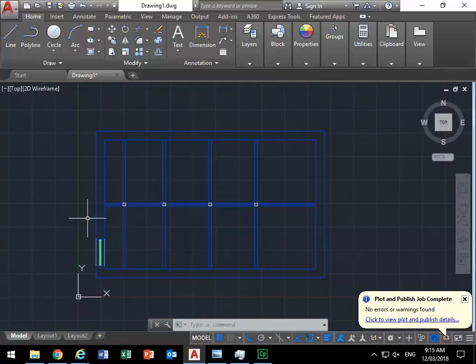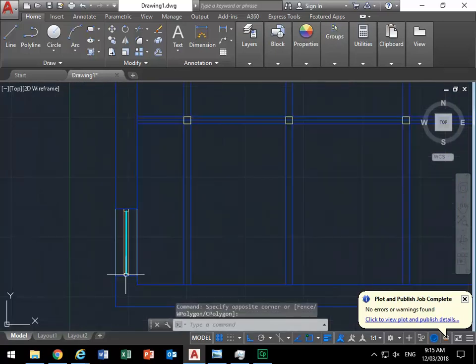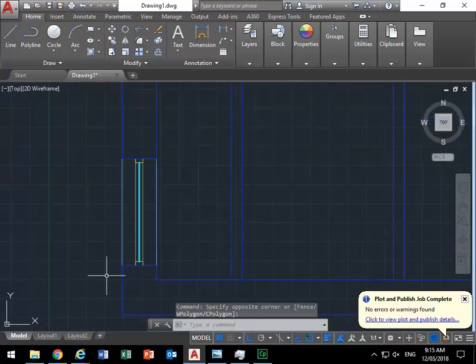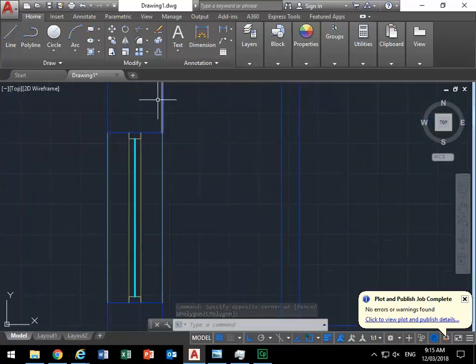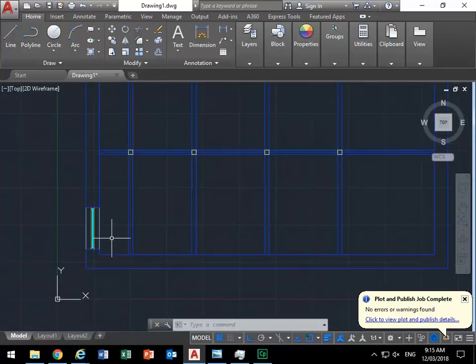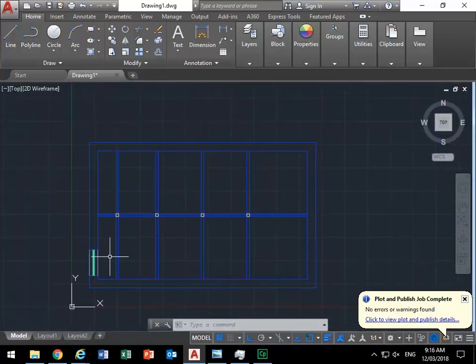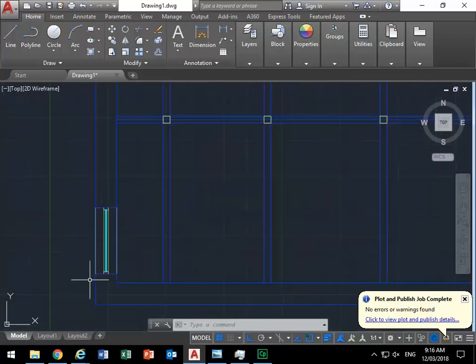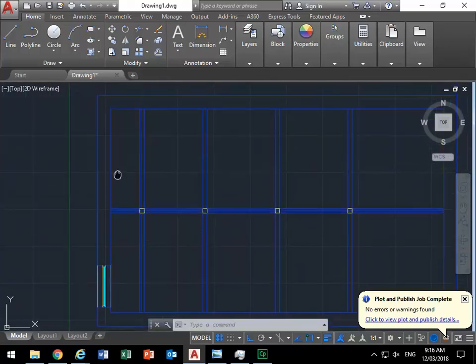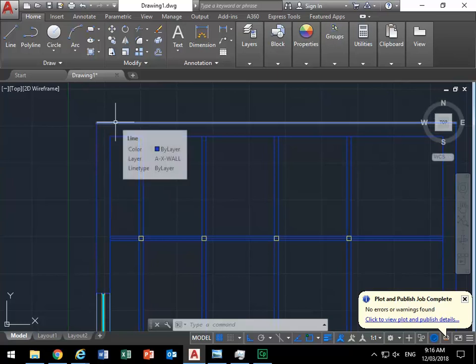So going a bit faster now, I'll put in the other windows, and so if you set it up properly, there's no point just doing part of it. You need to do it all properly before even worrying about copying it. Because if you do it in a not so good way and then copy it and try and get it all finished, you're going to have to come back and fix all of the windows. When if you get it right on one, then of course when you copy it, you don't have to go and fix anything. So here I'll start with the openings.